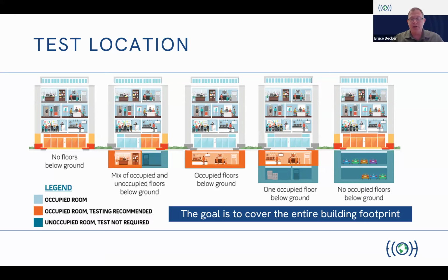If you've got a parking garage in your building, which some of the larger commercial buildings do, you don't need to test that. However, if you've got a security guard and a kiosk down there, that would be a workplace and they would need to at least test the kiosk, right? Or there's a lot of car washing and detailing companies down in some of those parking garages. That's their workplace. That would need to be tested. Okay. And an occupied area, or what's deemed occupied, is a room or an area that an individual occupies for 4 hours a day or more. Okay.